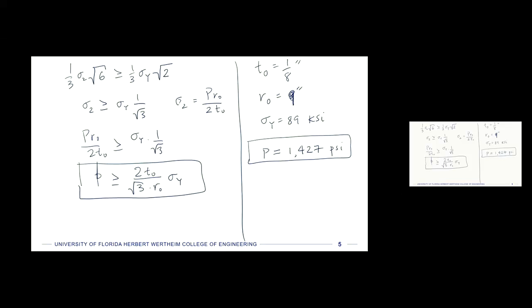So it's a fairly high pressure. It's not, you know, ridiculously high, but think about car tires, compressors you might have worked with, building compressed air, right? This is much higher than most of those. Okay. So this is where most of your solutions will end, right? If you've studied failure criteria in the past, because we have decided it's no longer in the elastic range. It's yielded at the outside somewhere, and that's where we stop. We calculate factor of safety and then move on, okay?